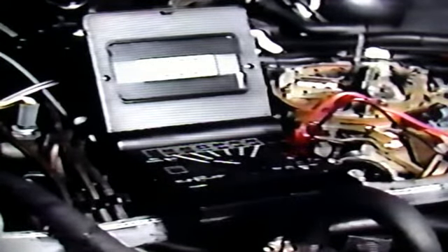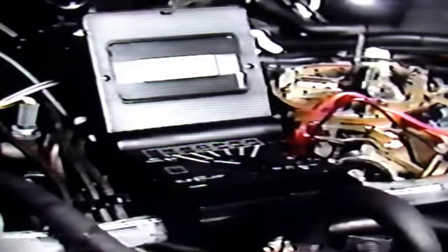You'll notice that our test engine is set up a little differently. It won't cycle at all until after it has been started. GM wants us to measure the voltage when the solenoid is not cycling. So we'll take our meter over here, connect it to the dwell lead, and ground the meter somewhere over here. The meter shows 12 volts. We look at the chart and find there are 2 options, under 10 volts or over 10 volts. We're over. So we go on to the next box. Check voltage at ECM terminal 18.